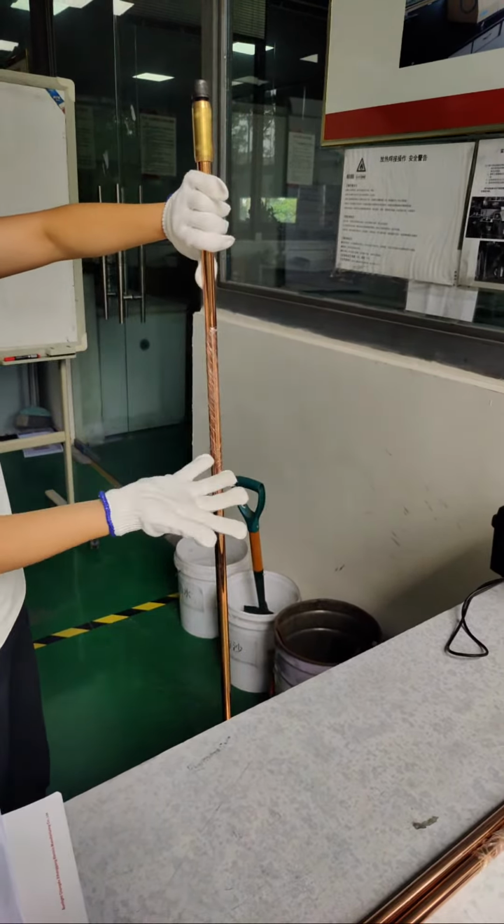Okay, camera gets closer to the bending part. Now you're seeing a 5 times visual inspection of the bending part. You see, there are only some marks which were bent by the machine, but it doesn't have any cracks, doesn't have any peeling off. So this is totally qualified to UL and also the IEC standard.